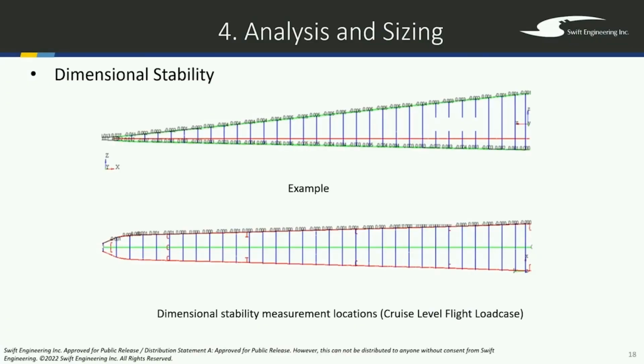We did try out a lot of different options for core, height of the core, type of core. All that was run really fast in Hypersizer. I think all of you do that on a daily basis. But these are just 2 of the dimensions that we're measuring all the way. So every 12 inches, they had a criteria. So every 12 inches, you couldn't be within 48 thou difference. So as you can see, it's well within that in both dimensions, the vertical plane and the lateral plane.